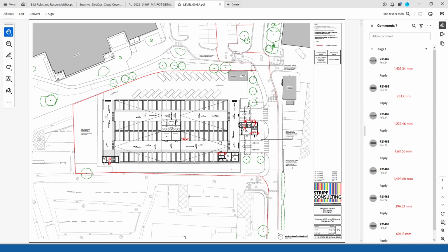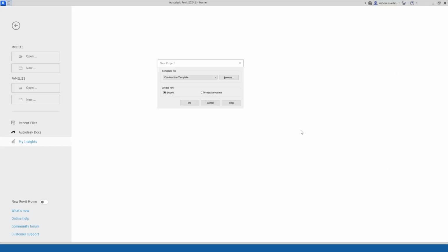We call these general company standards. Okay. Each company has its own standards. When you link or open a Revit model, all these standards will automatically be loaded into those Revit models, discipline specific. Okay. So obviously, let's say I'll take an example of creating an architectural model. I need to use architectural, structural, or mechanical, based on the design scope which you work on. Okay. Usually, for architectural you should not use structural. Okay, you should not make that mistake. So based on the design scope which you work on, you can use those templates only when you work on it.